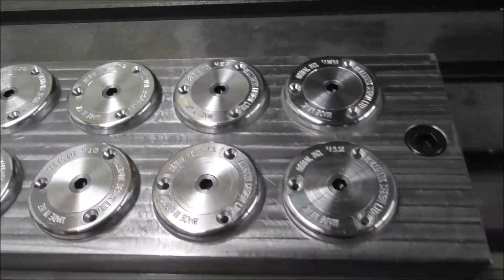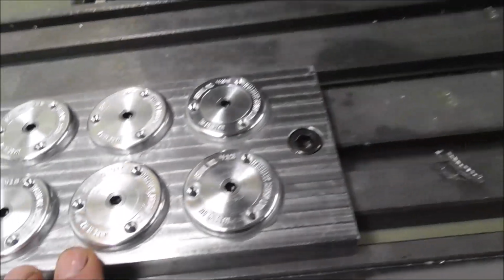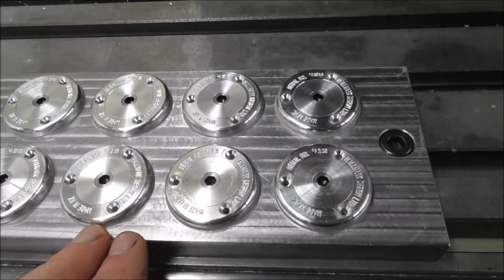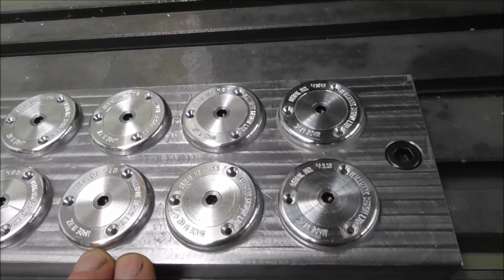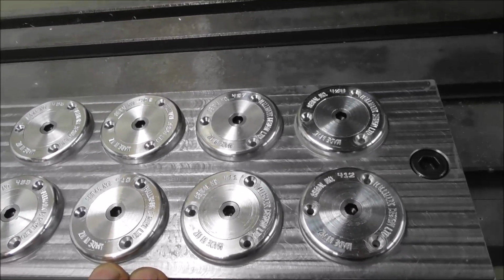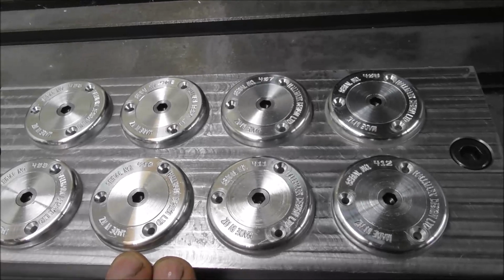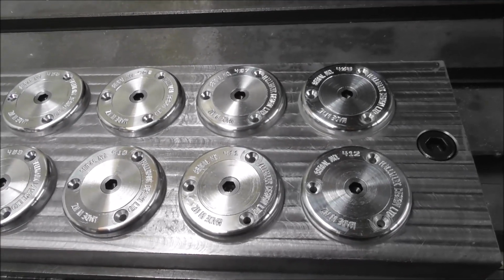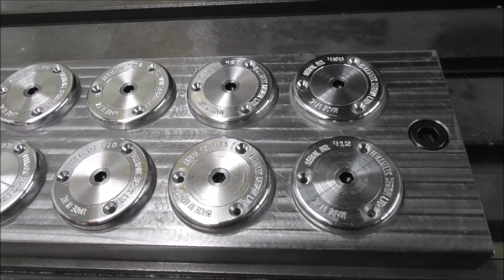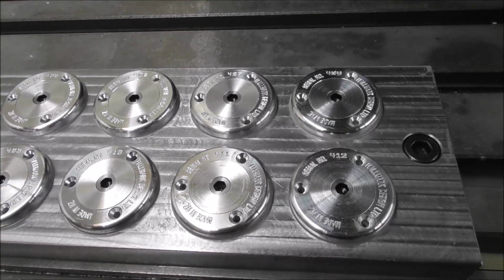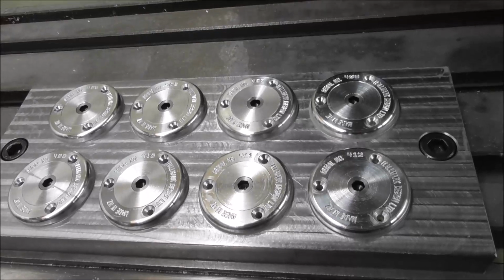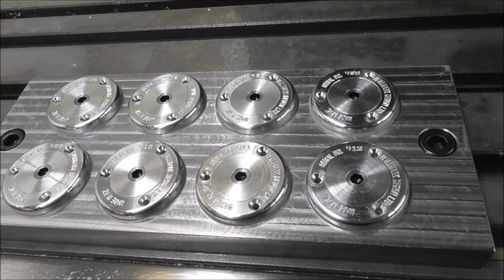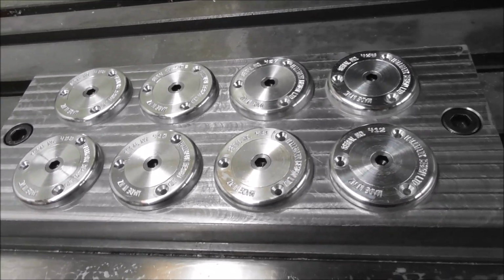That was really satisfying. So I quickly made a little mild steel plate and some clamp washers, set it up and learned how to use subroutines to cut the different parts, to cut the different work offsets, and then use the sequential serial number system. And I found that quite challenging. For my practical non-academic brain, it was a bit of a struggle, but it's come out well.